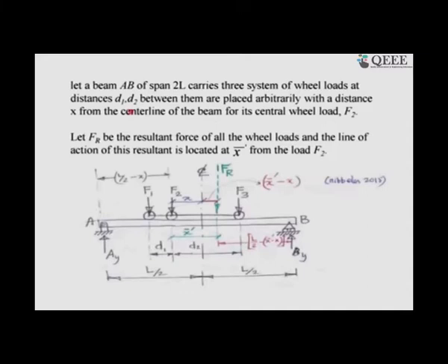Yes, we have also seen that one of the loads should be equidistant from the geometric center line from its resultant, the sum total of all the forces. So, they should be equidistant, and that is the position which can make it maximum, but you need to investigate it for other loads if there are trains of loads.